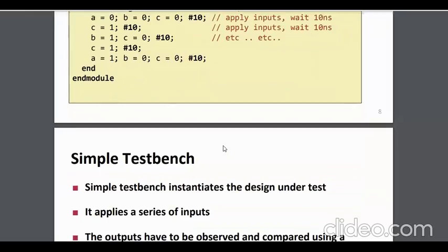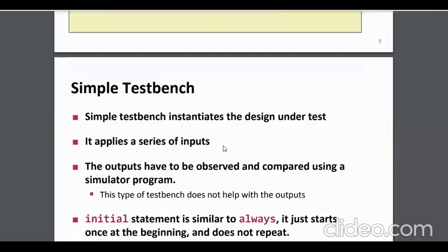What you will be doing inside your test bench, after writing your design, keep in mind, or make a note of it. First thing is, you need to instantiate your DUT inside your test bench. Until now you have been compiling and simulating your DUT only in your tool, ModelSim I guess.